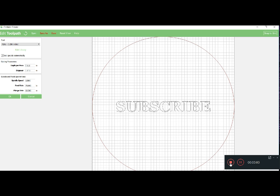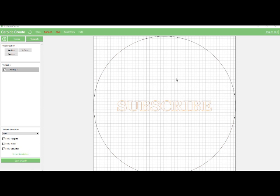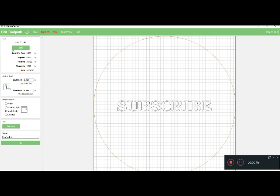So we're going to show you how to change all those, but let's look at the 201 bit first. So what I'm going to do is click out of this, come over to my circle, and go to the contour, because we don't want the V-carve. V-carve, again, is good for your writing.